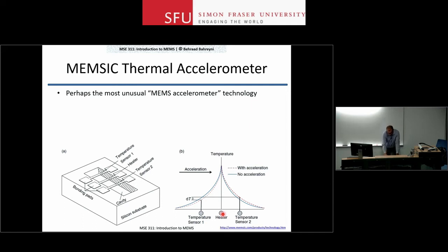And now what happens here is that the heater will heat up the air or the gas above it. As the gas heats up, its density becomes smaller. So when you apply an acceleration, the more dense gas, the cool gas, will respond more strongly to that acceleration and move a bit more than the light gas, the heated gas, the hot bubble that you have.